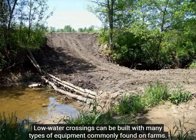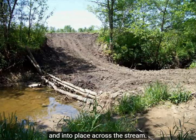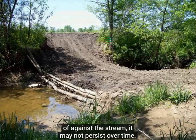Low water crossings can be built with many types of equipment commonly found on farms. Front-end loaders or a blade on a three-point hitch can easily be used to push material around and into place across a stream. However, unless a ford is placed at a site that offers natural stability and built according to a few design principles that work with instead of against the stream, it may not persist over time.